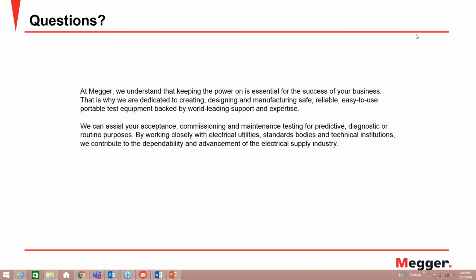So basically, it's not the only test you want to do. If you're doing an impedance test on a NiCad battery that's at end of life and its impedance has shot up, yes, it's going to show you have a bad battery. However, if you get a good measurement on a NiCad, a low impedance reading, it doesn't mean that battery is good. It could be close to end of life and you don't know it.